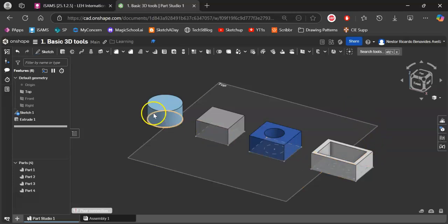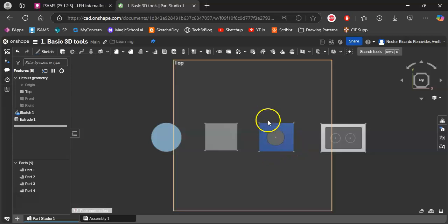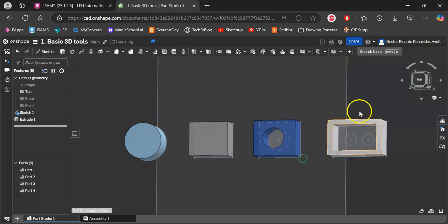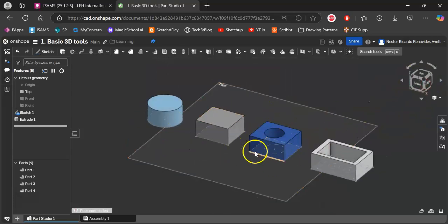Whereas, as you can see here in the first 2 examples, with the circle and the square, I created a cylinder, and I created a kind of cube in here. Very, very basic understanding of this. A circle is a closed shape, so you extrude it, you obtain this one. A square is a closed shape, you extrude it, you obtain this shape. But in this one, if you remember, what I drew was a rectangle, and inside I drew a circle. The system easily gets it, and will make this shape with a hole in the middle, just like with this frame.